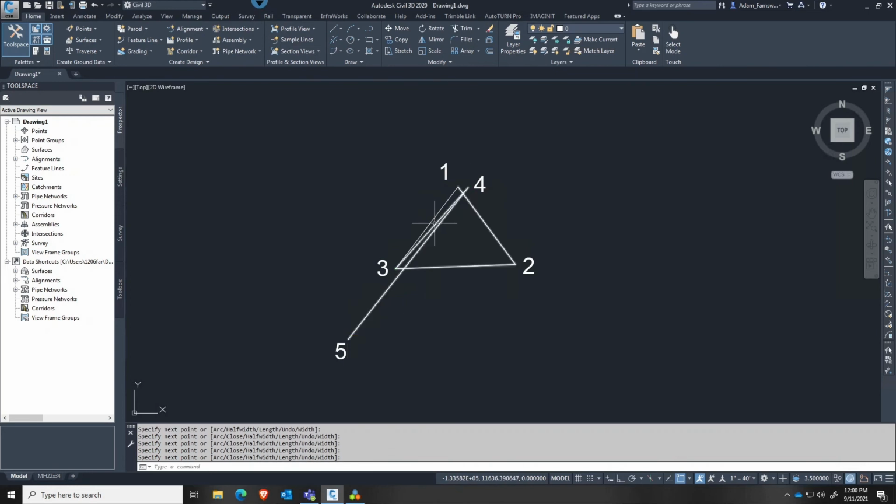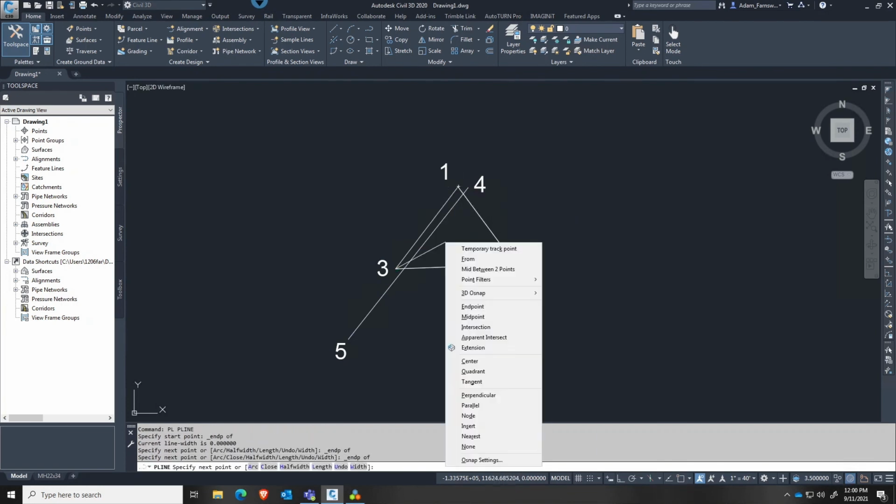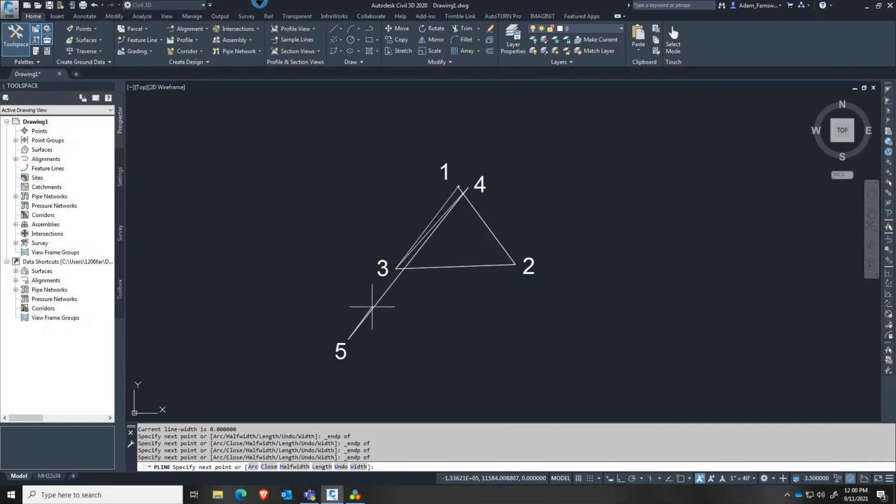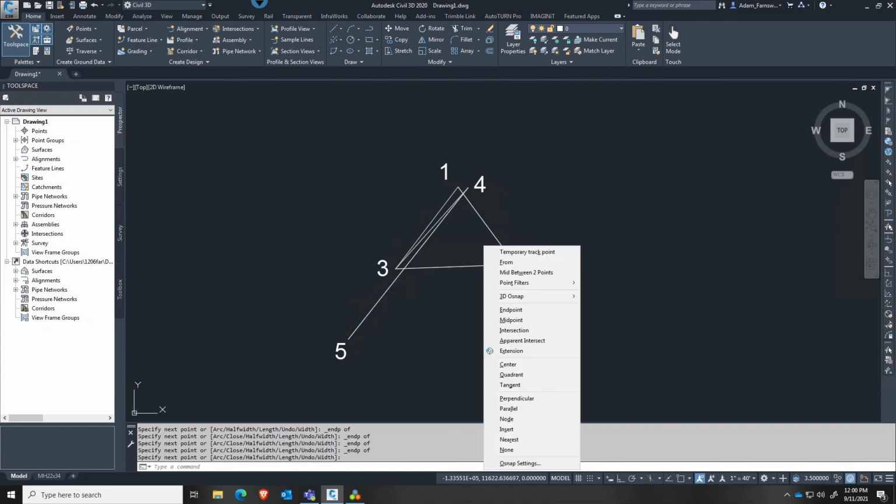Okay, that was pretty quick, but I'm going to turn off O-snaps, start my polyline, right-click, snap, right-click, snap, because I don't have to worry about snapping to anything else. I can go much faster using the shift right-click method. I have all of my various snaps, and I have these underlined. I know what they are. I've memorized the letters, so I don't need that anymore.